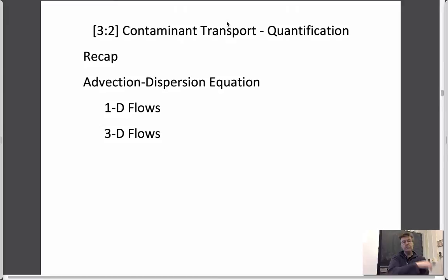Right. So we made the case before that we've talked about these two very discrete entities. One is how fluid travels in the subsurface as a free phase. It matters whether it's a DNAPL or an LNAPL. And based on knowing which one of those it is and some features of the porous medium it's going into, we think we can say something about the saturation distribution as a free phase. So that provides a source. It's stuck there. It's held by capillary forces.